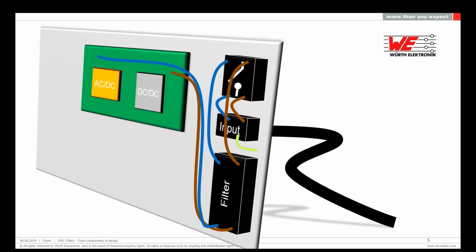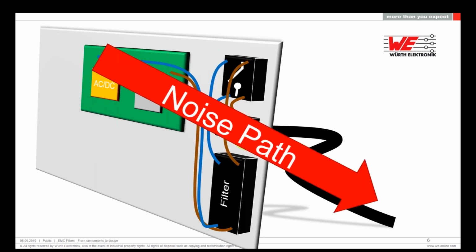What we can see here as evident, because I made the schematic very simple, so there were more components on this board, is that now we have some kind of inductive coupling in the circuit, creating basically a noise path for the noise to go back to the mains line.